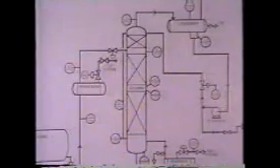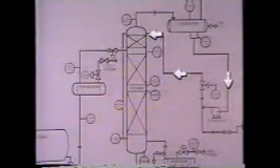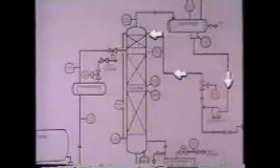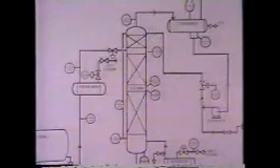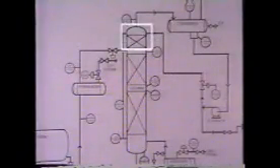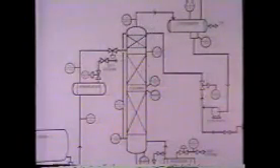As you know, reflux is the overhead product that is pumped back into the column after it's been condensed. When the column is being started up, there is no liquid at the top of the column, and all the overhead product is returned to the column as reflux. In this way, there will be enough liquid at the top of the column to ensure vapor-liquid contact.